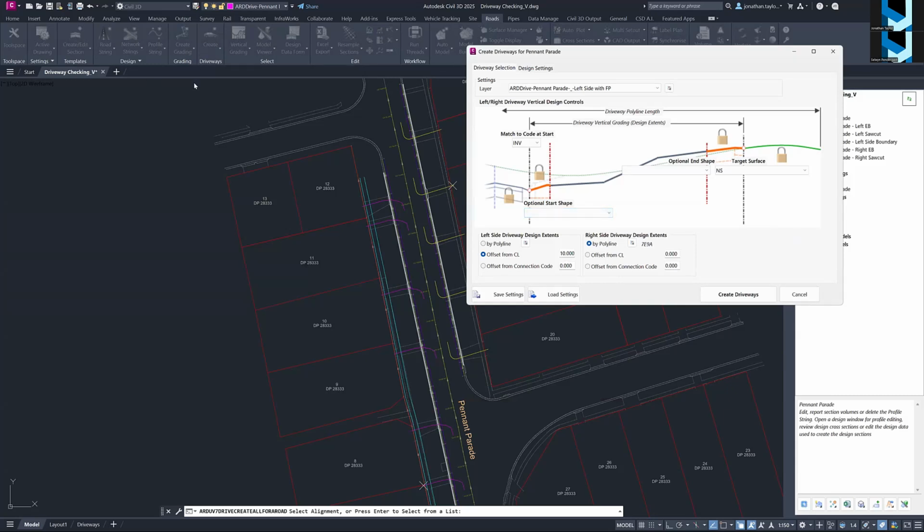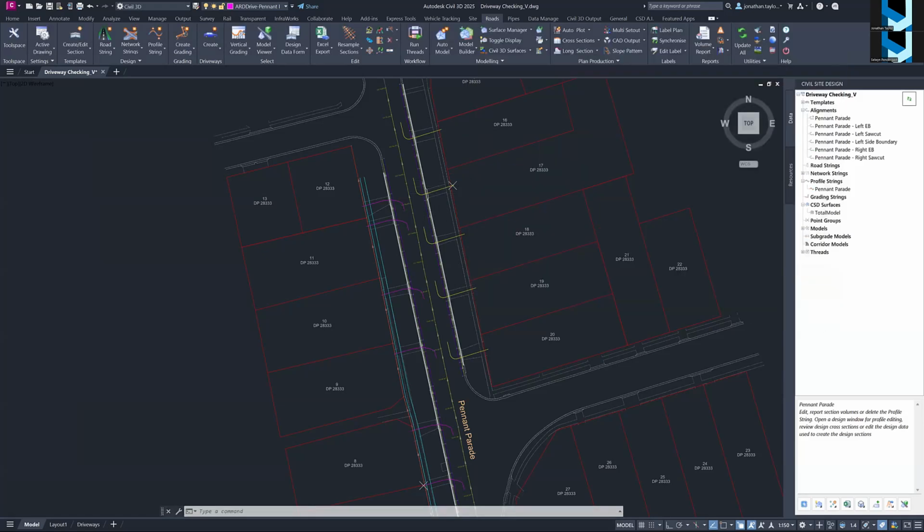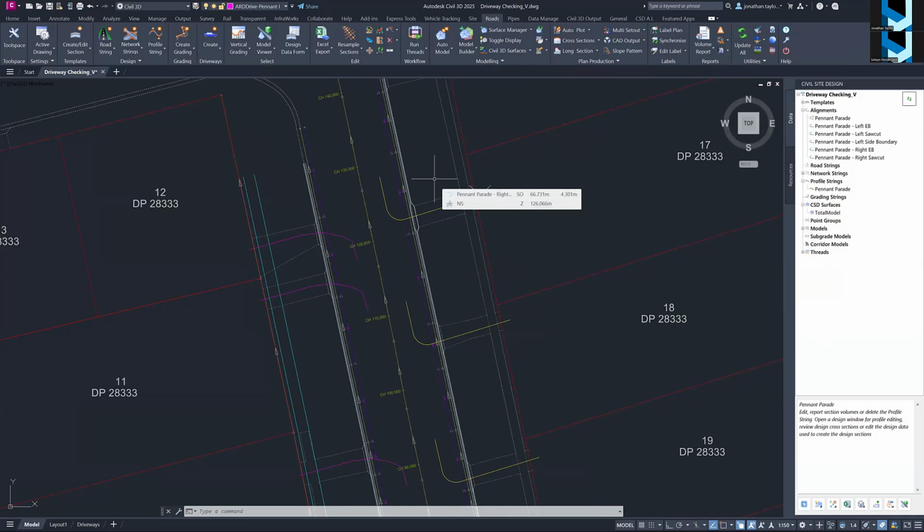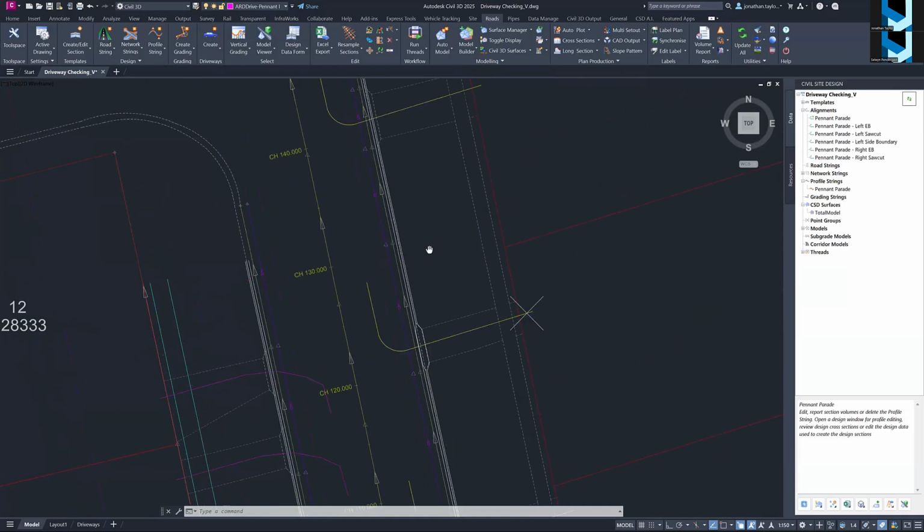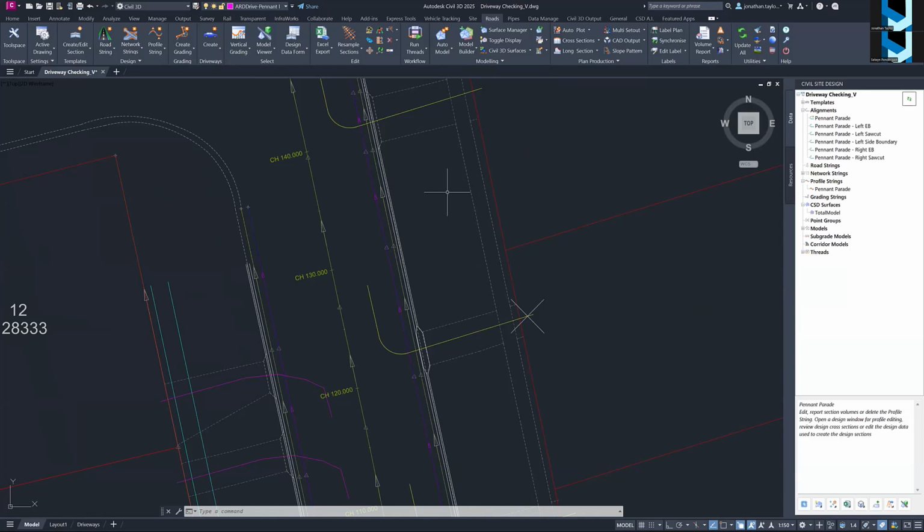Thanks, Jonathan. Another one, in the custom layback script that you showed a little while ago, is it okay if the end changes overlaps with the start of the next layback? Yeah, good question. I would probably try and avoid it. I actually wrote that script, and it does calculate the changes as it goes through. But the fact is, you are telling it to do something in the chainage range of another variation. The two of those could end up conflicting where one doesn't work for that specified chainage range. I would try and avoid it.